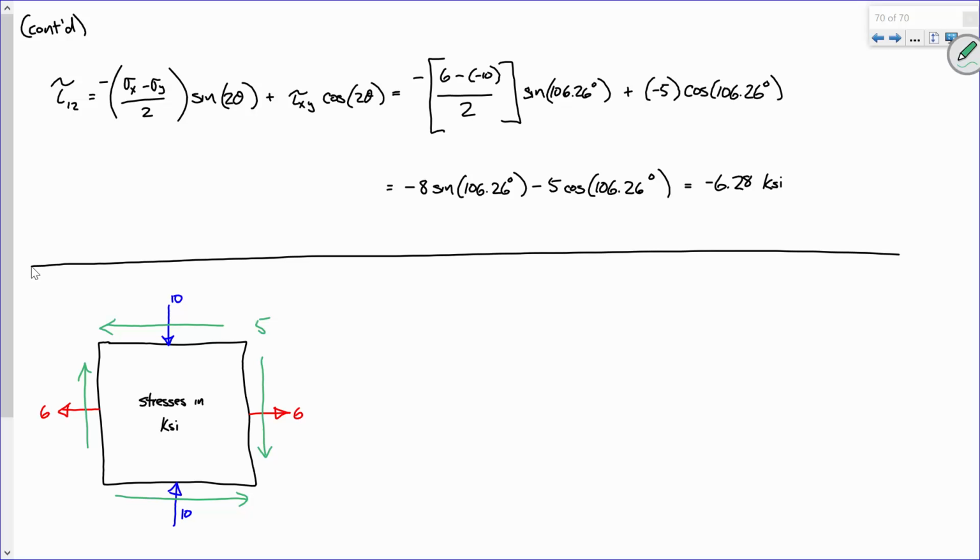One of the interesting things about shear stress that you're going to see in a second is that the signs don't really matter. Whether it's positive 5 or negative 5, it doesn't really matter. It's all because of the nature of the math, particularly when it comes to Mohr circles. We're going to find later on that maximum shear stress is equal to the radius of that circle. The radius doesn't matter what way it's facing. So we'll see that in a second.